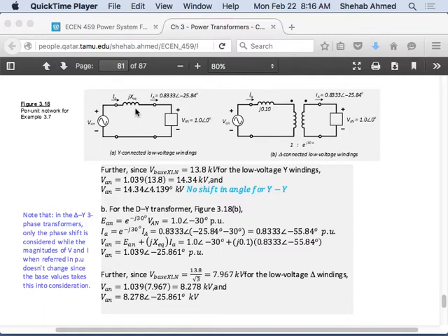We calculated the impedance. They gave us the impedance of the transformer was j0.1, and since it was in per unit, it does not matter, right? It does not matter if it's star-star, delta-delta, star-delta. If you're given the impedance in per unit and it's your transformers, you properly chose the base, then the ratio of the magnitudes of the turns is always 1, right? Only when there's a delta-star, there's an additional phase shift, but that does not affect the value of the impedance. So the value of the impedance at j0.1 is the same here and here.